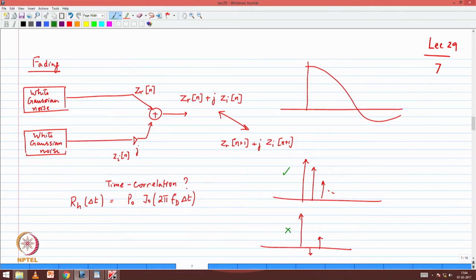Okay. So this is where signal processing helps us. Correlation in time corresponds to coloration in frequency, because if I have an autocorrelation which is an impulse, that means there is no correlation. In the frequency domain, it is flat. So if I have a correlation that has some time domain behavior, then I would see some coloration in the spectral domain.